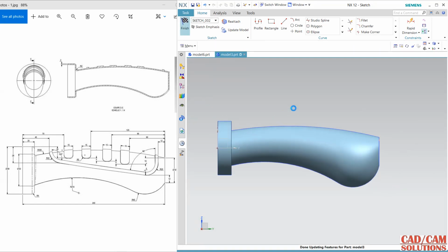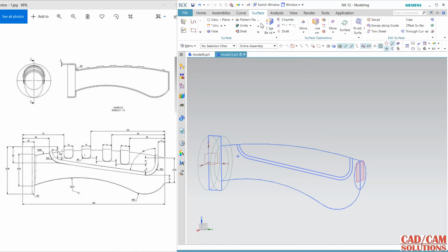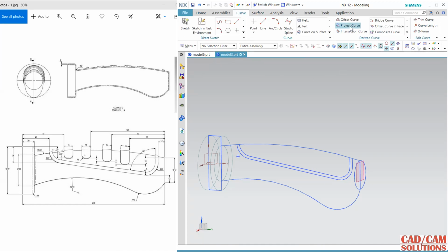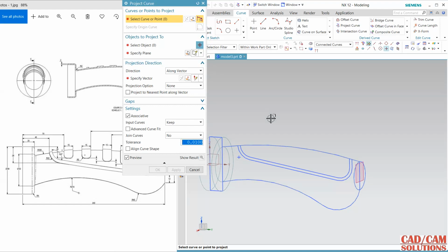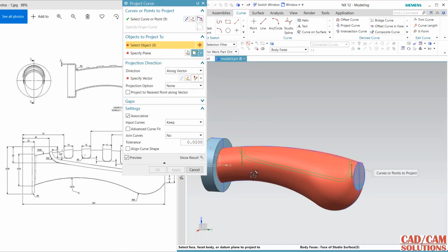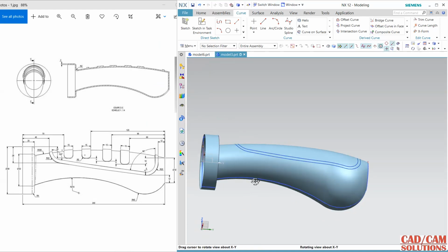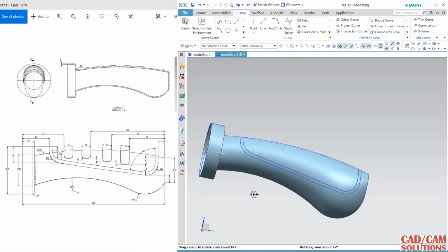And same here I'm doing, and close. Now finish and change it to wireframe, and go to surface, sorry, go to curve. Here it is, projected curve, projection, and the curves are 1 and 1 2, and my surface is this upper one, and projection is along this direction, and make sure to project on both sides. Okay, the projection is on the surface.